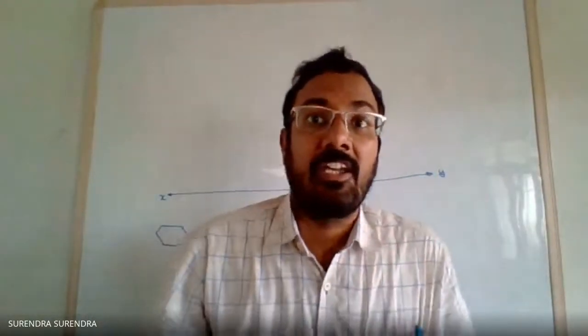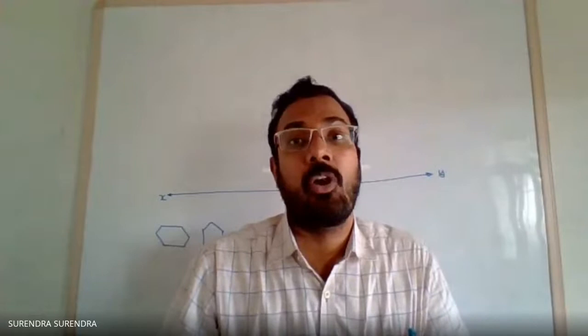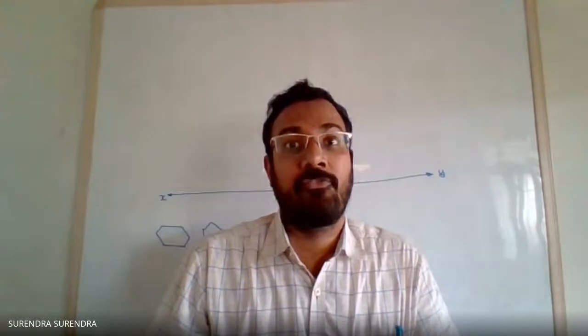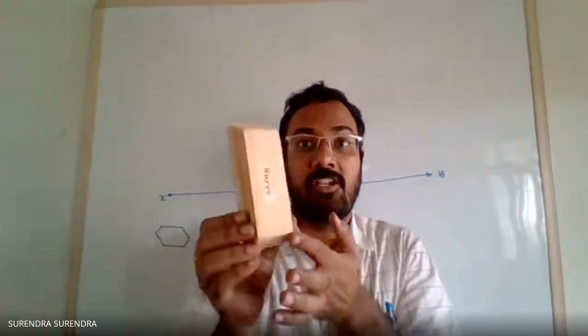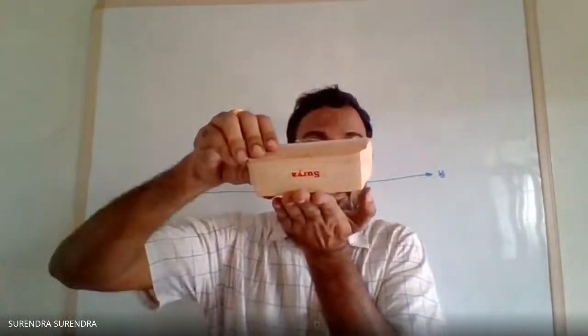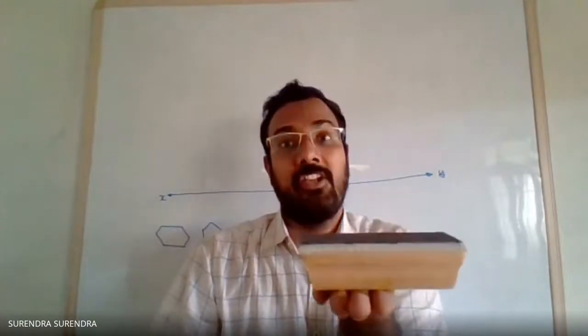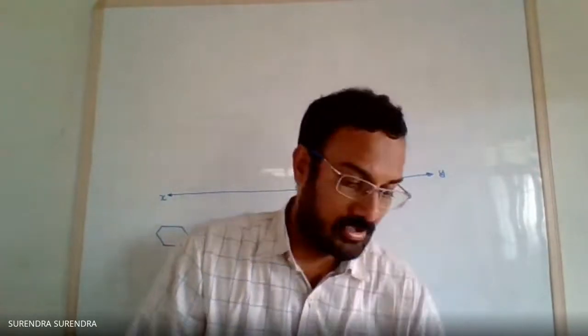So whenever in any problem it is given that it is resting on a face, it may be a prism or pyramid, you must rotate the solid based on the edge. If you rotate the solid based on the corner, it will rest on an edge, not on a face. If you rotate based on the edge, it completely rests on a face, rectangular face or triangular face, depending on the shape of the solid.